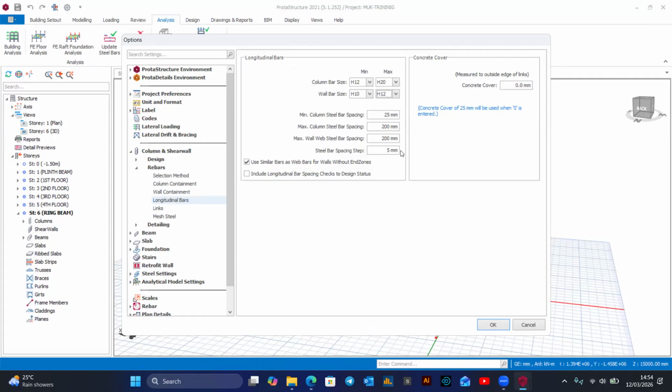Now, those wall loads which we put on the beams, they are calculated internally. And then they are transferred onto the beams. The beams take them to the columns. But the walls I meant walls like reinforced concrete walls. They are not masonry walls. So the walls which are designed here, they are reinforced concrete walls, like lift shaft walls, basement walls, retaining walls, those kinds of walls. Yeah.